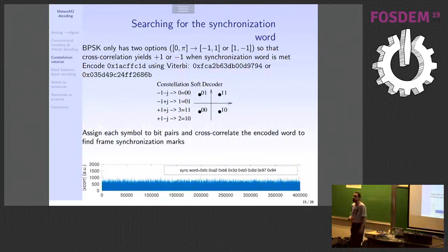What is the sequence? Well, as we did for GPS, now I should be able to correlate my received signal with a synchronization word after encoding by Viterbi, and it miserably fails. You see absolutely no correlation peak. I cannot find in my QPSK signal the set of bits of my encoding word. Why is that?